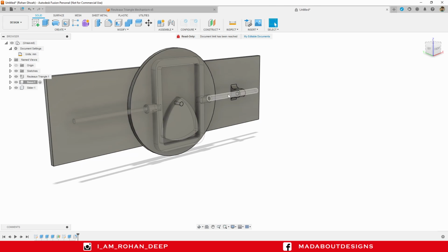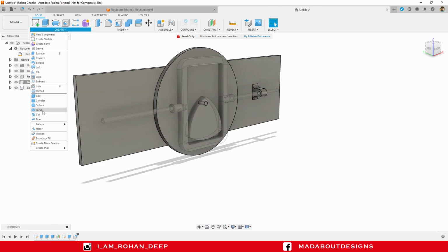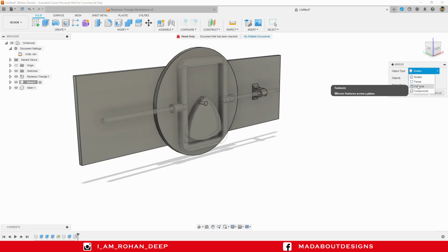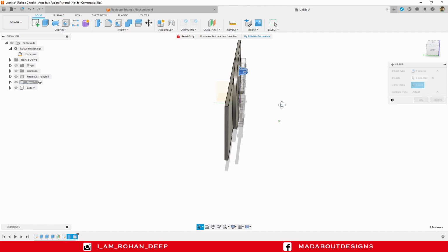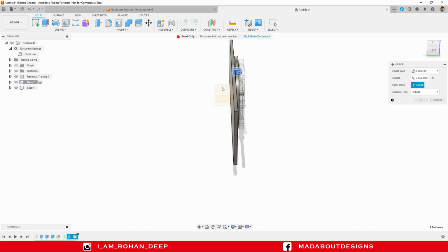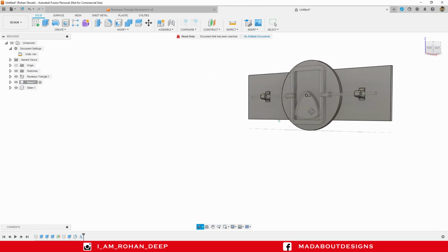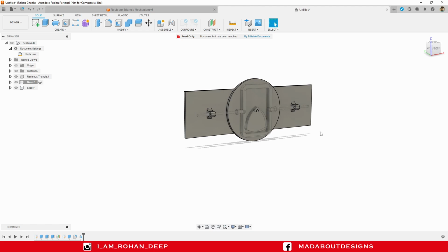Mirror this hinge on the other side. Click on mirror, object type, features. Select the extrude and the fillet from the timeline, and for the mirror line, select this left plane. Compute option, adjust, click OK. Here all of my components are ready.